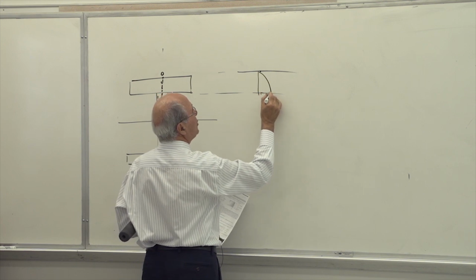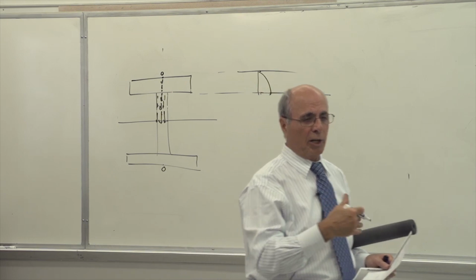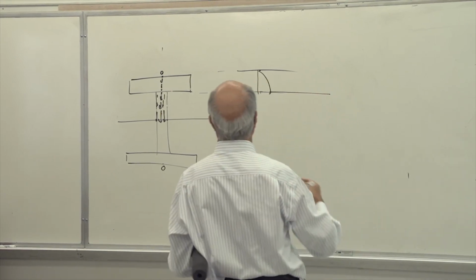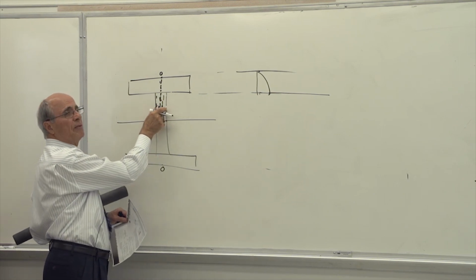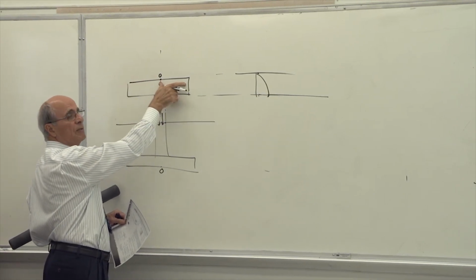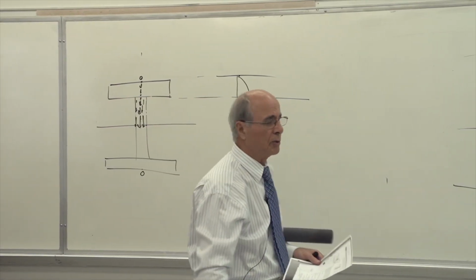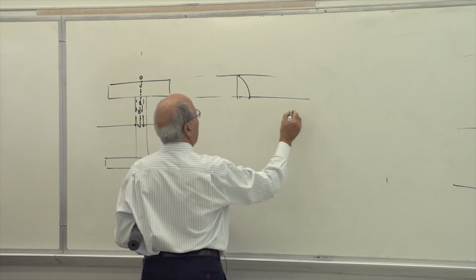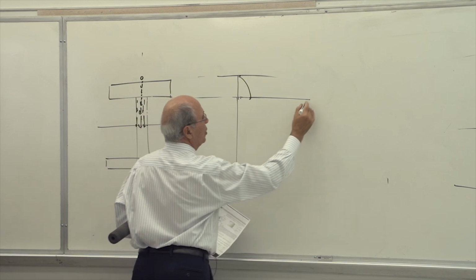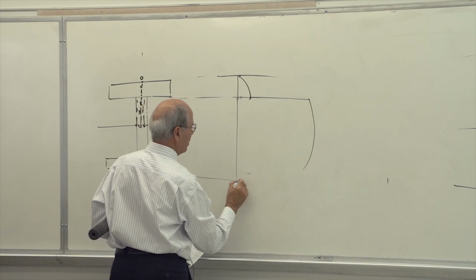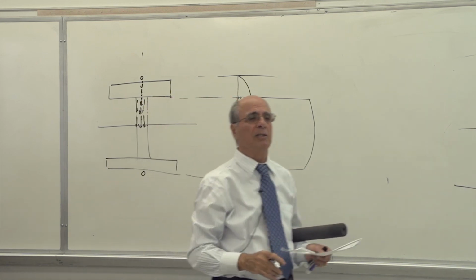But at that point, suddenly it's going to have a ratio of 1 to 10 or 1 to 15, depending on what thickness I give you here and what thickness there. Usually for a beam like this one, if this is 3/4 of an inch and this is 15 inches, you see how really huge the difference is between the two. And then it jumps, and then of course Q keeps increasing, but only a little bit. So it goes a little bit like that, and like that. So we have two breaks here, one here, one there, because of the change in the thickness.